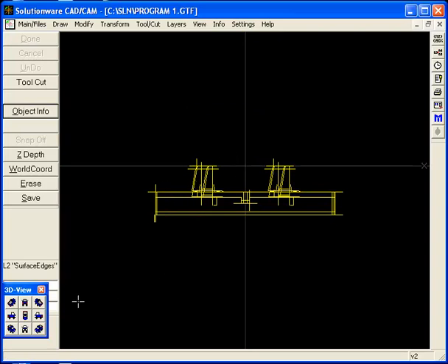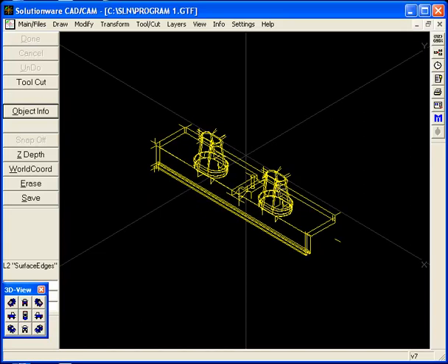And how we're going to be cutting this is, we're going to attack these two bosses by using surfaces, but we're actually going to be doing a projected macro cut, and this will allow us to do a regular simple 2D mill cut and then project this as a second step onto a three-dimensional surface, which are these two bosses and the flat part of this part. It will be clearer to you as we go, but the first step is we're going to do a 2D milling cut.